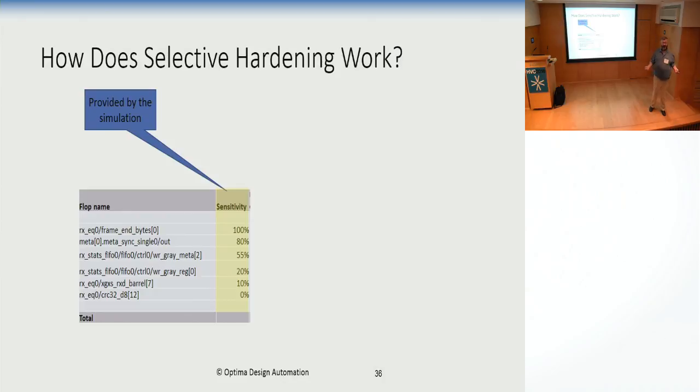If you want to go to the extreme, you can do a three-way TMR for each flop separately. Actually, if you just do these things, it will cost you more than a regular part, but less than having three parts separately. So hardening your flops, let's start with hardening all your flops, can cost you, I don't know, a 1.5x of your chip, because flops are not that big a part from the overall chip area. So if it's like 10% of your chip is flops, then you can go to 1.3, 1.5x area. Not so good, but better than 3x for the three-way redundancy.